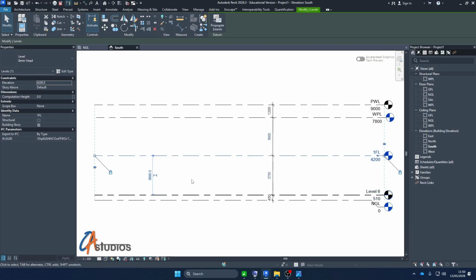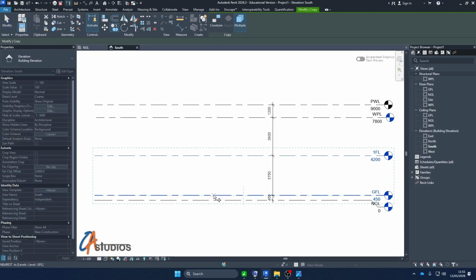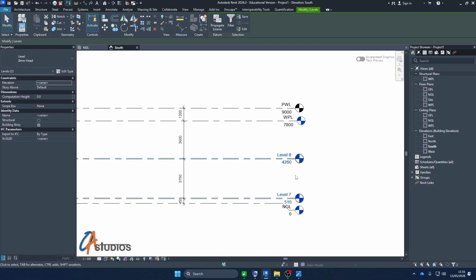I could have even copied them, so let's work smart. I'll delete this and select it too. If I select one item and want to select multiple, I can hold Control and you see the plus sign active on the cursor, and I select. Alright, and I'll click CO, and I'll just go up by 60 and drop for both of them.